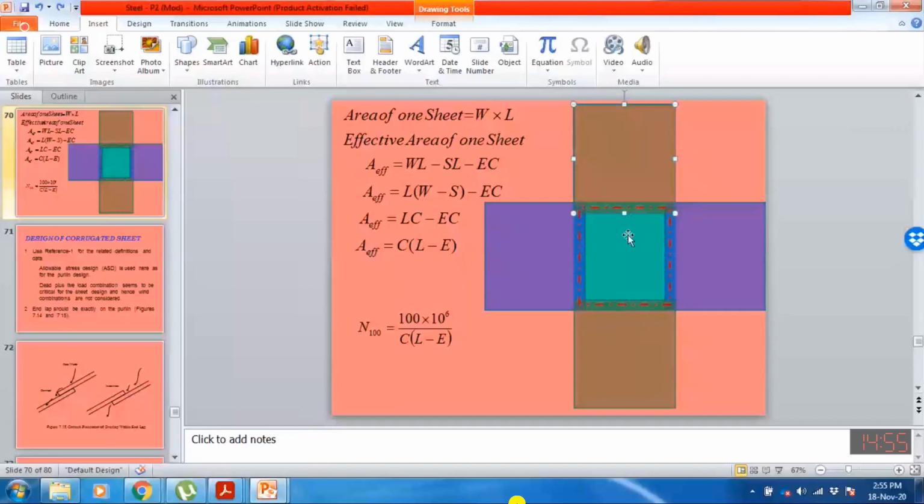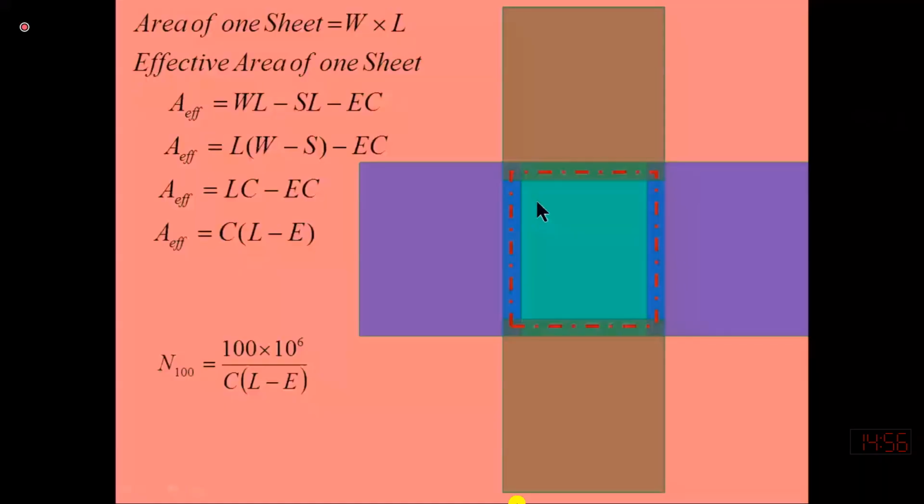Similarly, half of this end lap is provided by this sheet and half of the end lap is provided by this sheet. So the effective cover provided by one sheet is this dash line, which is lying along the center of the side lap and end lap. So this total effective width or cover provided by one sheet will be equal to...